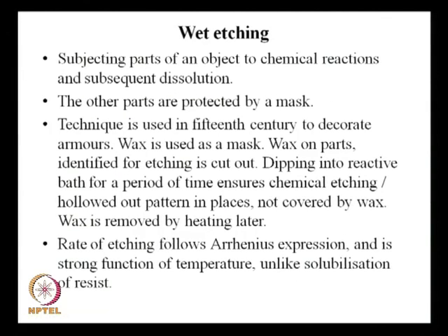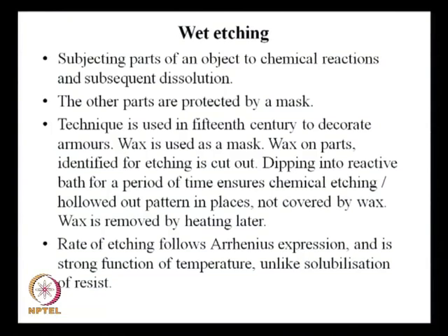However, this etching is a reaction. Etching is a reaction of silicon with the dipping solution. So, this rate follows an Arrhenius expression and is a strong function of temperature, unlike solubilization of resist. This is a very important point, you should note down that the rate of etching is a strong function of temperature. So, when you calculate how long you should keep the substrate in the etching bath, or when you consider the rate at which the etching will take place, that would be a strong function of temperature, unlike the solubilization of photoresist.